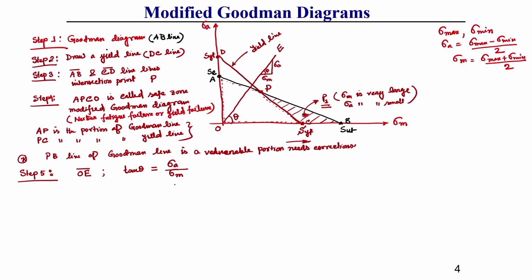Now, this amplitude by mean stress you can write in a different way. Let us take force amplitude divided by the cross sectional area of this component, and mean force divided by the cross sectional area of this component, then we can write this as Pa by Pm. This is in case of an axially loaded case we can write like this, Pa by Pm.